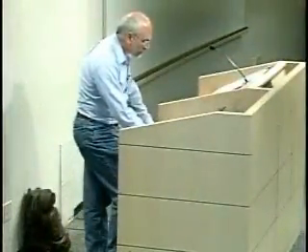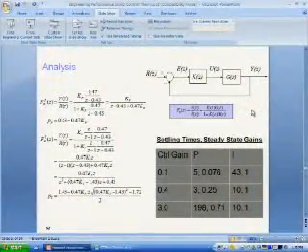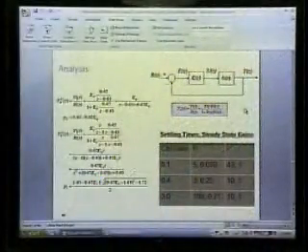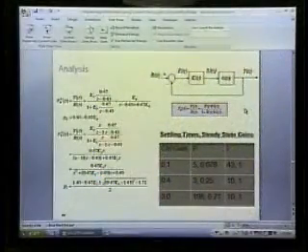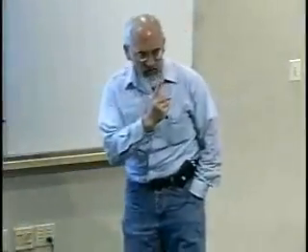For design, you'd go back and come back with the transfer functions. So let's go back to that sort of complicated slide with the transfer functions on it. Okay, so here we have the transfer functions, and let's just look at this one right here. That's with the integral controller. So we have just one parameter, Ki, that we want to look for. What we would do with our design is basically the following steps. We decide on some objective. We've got one objective we can work with because we only have one constant. So let's say our one objective is settling time.